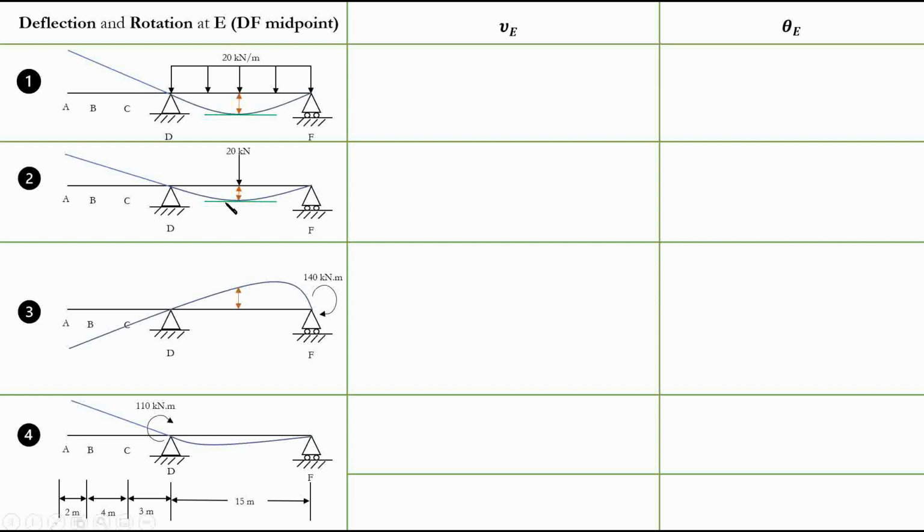Now for case 3, we have deflection like that, okay? And as you can see, it's not maximum, right? And that's the importance of drawing the elastic curve. We have a really comprehensive idea of what the sign of our rotation and deflection values are going to be like, right? It's going to be positive, negative, upward, downward, clockwise, counterclockwise. In this case, we will have an upward deflection.